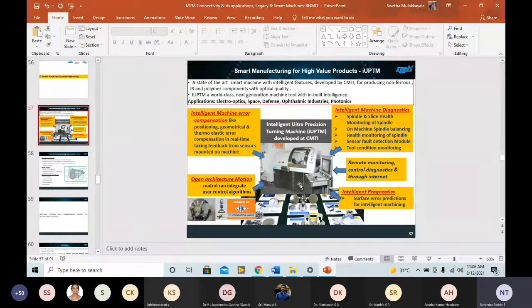But in production environments, these machines are not widely used because they are very expensive, 5 crores each. They cannot afford this. They use very low cost machines like 10 lakhs, 15 lakhs, 20 lakhs, turning machines I'm talking about. Generally they claim 5 micron or 10 micron. But such machines also you want to give value addition. If you can rightly map these thermal errors, then you can improve the component accuracies. Yes, that's how we have explained to you, sir.